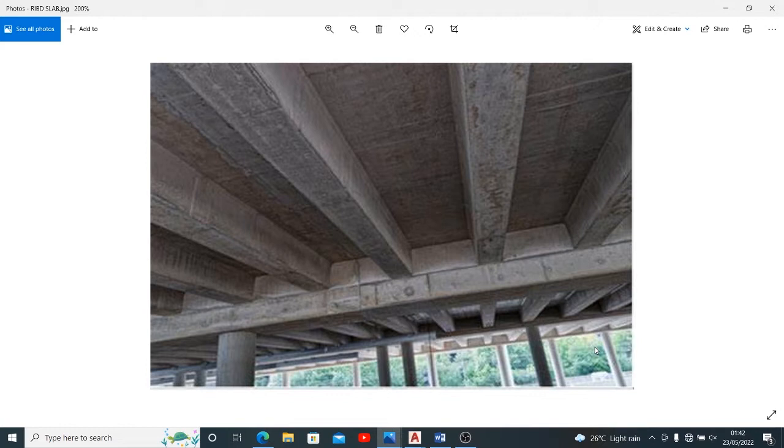In places where you might have to consider other kinds of slabs, for span issues where you need to use a slab without having interior column support, you would try to consider a rib slab. And where you want to minimize or reduce loads, you can also use your rib slab. And if you want to maintain cost while keeping everything intact, you can use a rib slab over a solid slab.